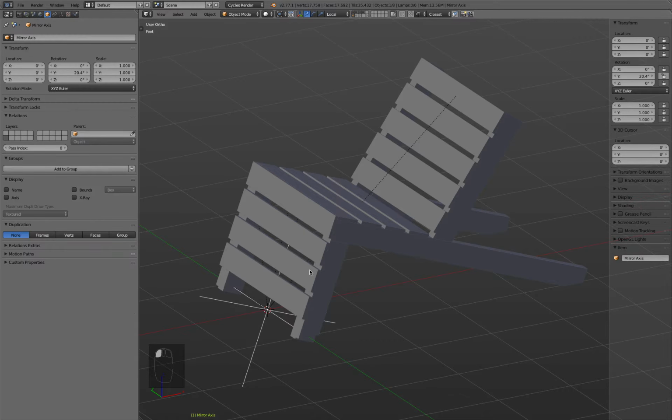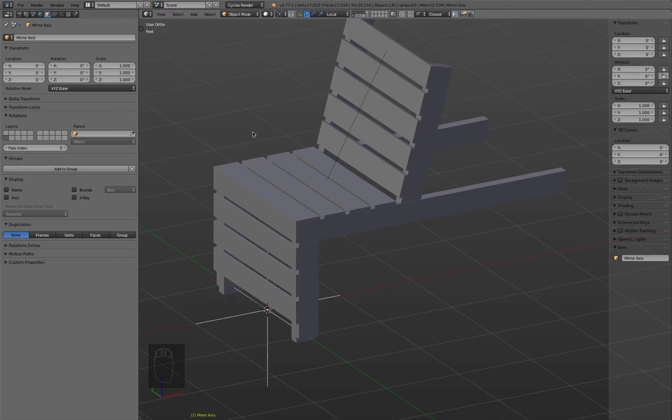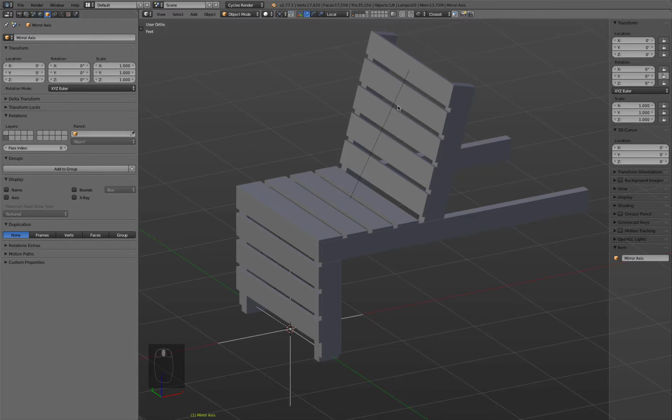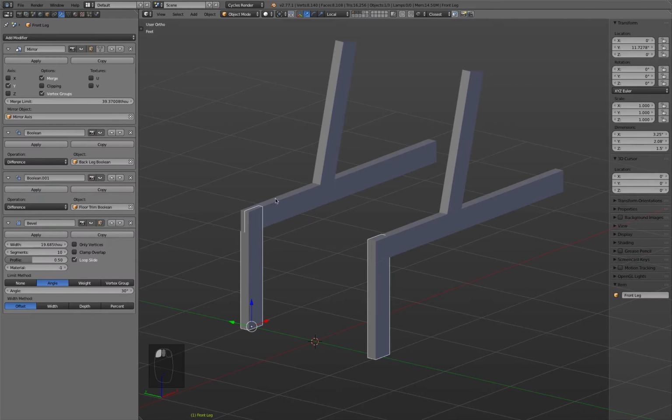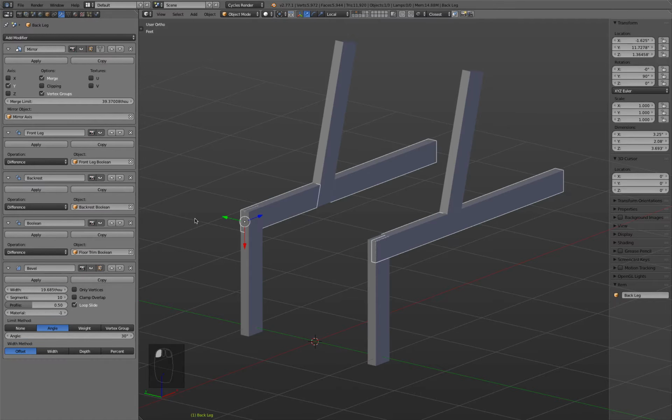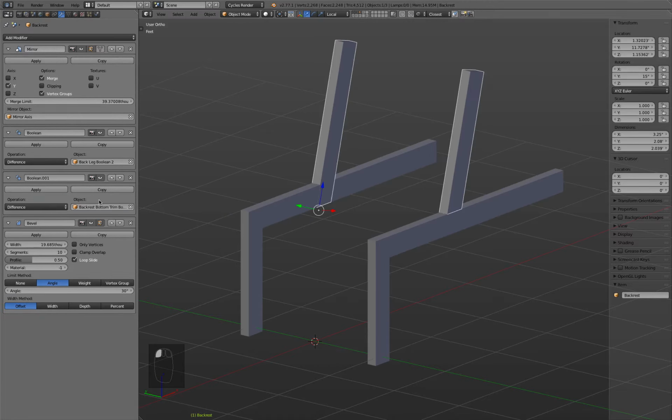First, because we have this nice parent and child relationship, I can rotate my complete assembly back so it's nicely oriented by rotating my empty. Okay, then we can hide everything. And what we will do first is turn off the bevel, and then we will remove, for example, those Boolean targets.